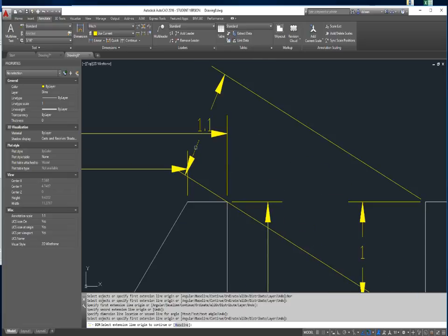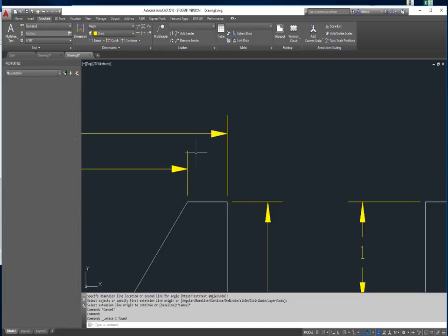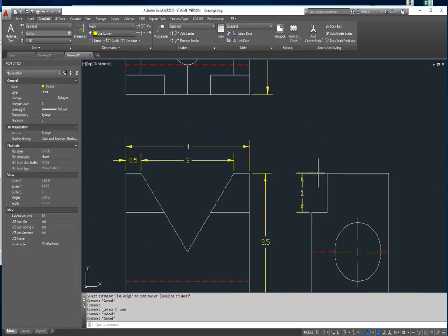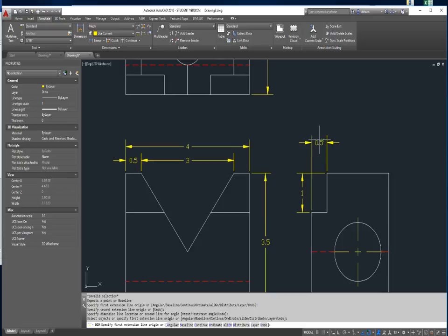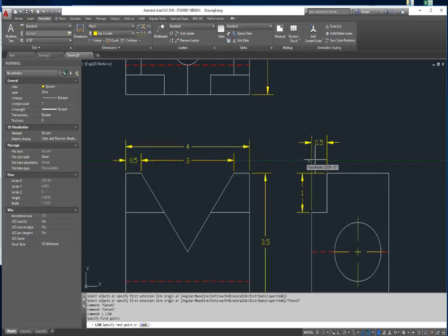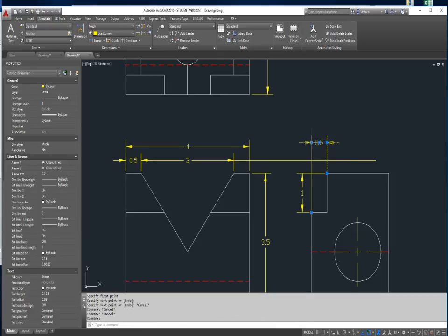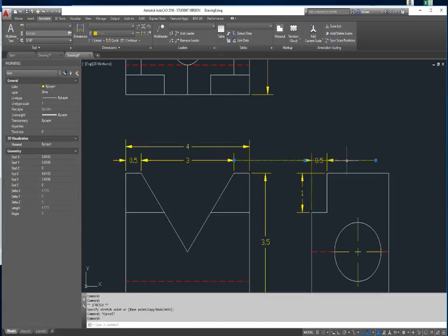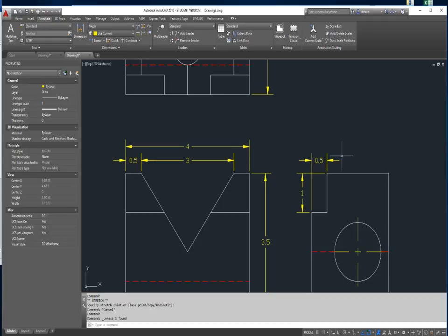Well, in later versions of AutoCAD, it's helping you draw those dimensions. So if I do a dim horizontal from here to here, and I drag that up, that's all well and dandy. It's not quite lined up, but if you wanted to line it up, you just draw a line coming straight across and put that down on that intersection. And then that'll look pretty good.